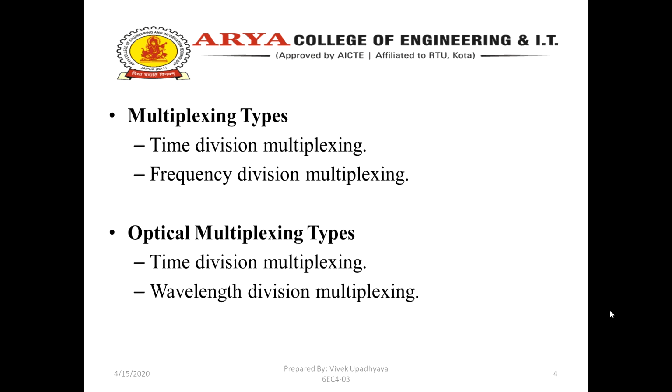First of all, the concepts of the WDM and the DWDM. If we talk about a point-to-point link with a single fiber line, there is an optical source at the transmitting end and an optical detector at the receiving end. With such a scheme, if signals from several optical sources are to be transmitted, each one would require a separate optical fiber.